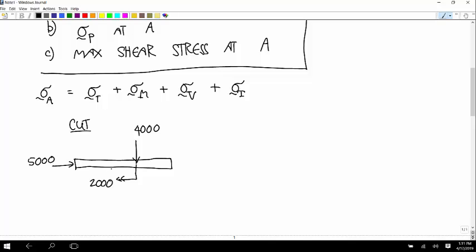If the total mass of the whole beam is 50 kilograms, the mass of the cut piece, we're dealing with 3/4 of the length, so 3/4 times 50, so 37.5 kilograms. And what's that times 9.81?